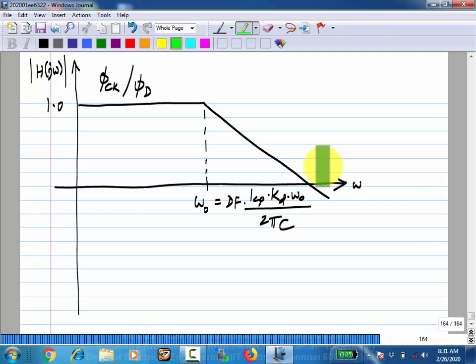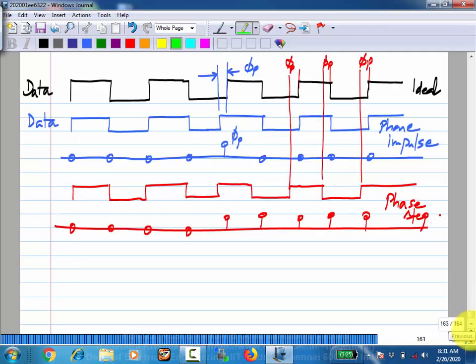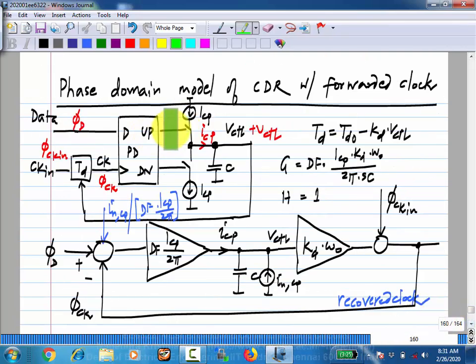So this kind of time domain visualization is very helpful and important, and it makes sense that this detects the phase, and then that has to charge the capacitor. So let's say it measures the leading phase, it has to charge the capacitor, it will charge it by a little bit, and then it will move the phase by something. That phase may not be exactly what you want, so it may have to move it further. So if you give it enough time, it will eventually track the input phase. On the other hand, after the first cycle, it corrects it. Let's say this phi d has gone, I mean the edge location has moved rapidly in the other direction, then obviously this tracking will not be correct. Is this okay? So that's the meaning of this low pass stuff.